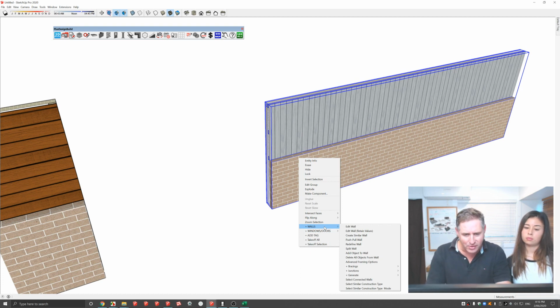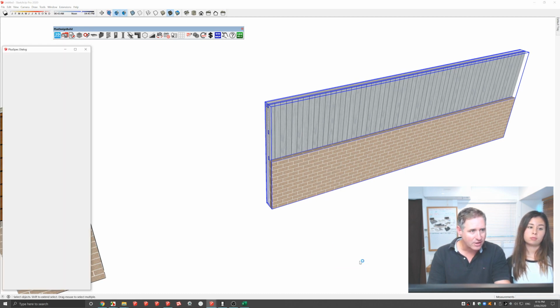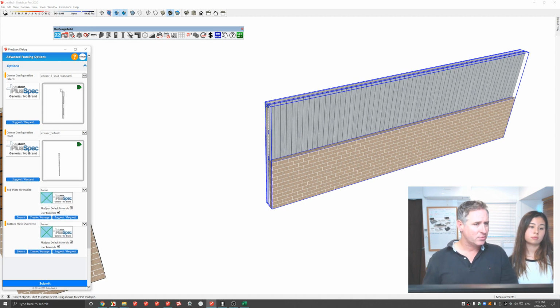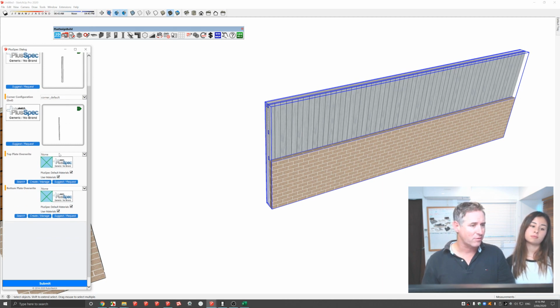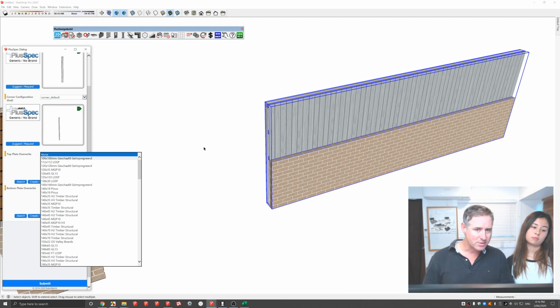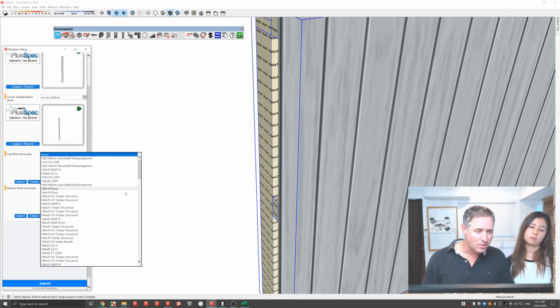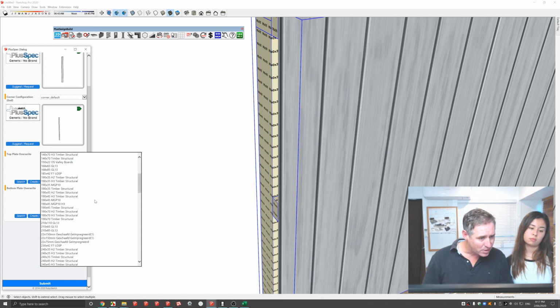So I'm just going to have a quick look through there, and what I'm looking through is walls. Just edit wall? Yep, so right click, edit wall. No, it's actually advanced framing options, and I can add bracings, junctions, generate, but I think there's actually something else. Advanced framing options, and you'll notice I can change whether it be a California corner. I can change the different types of things. I can overwrite my plates, and maybe, for instance, what size timber did I use here? 90 by 35. Obviously, if yours is imperial, you can change that as well.